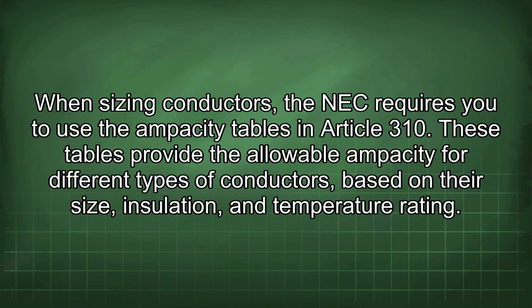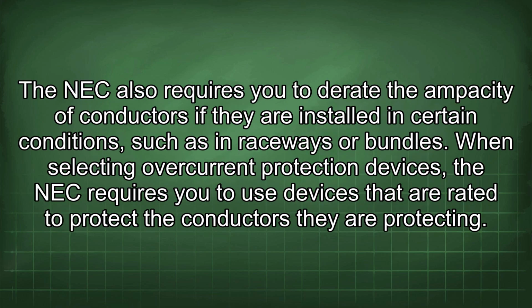When sizing conductors, the NEC requires you to use the ampacity tables in Article 310. These tables provide the allowable ampacity for different types of conductors based on their size, insulation, and temperature rating. The NEC also requires you to derate the ampacity of conductors if they are installed in certain conditions, such as in raceways or bundles.